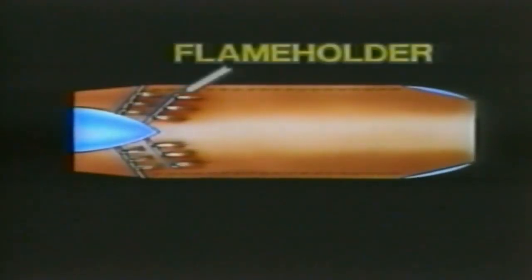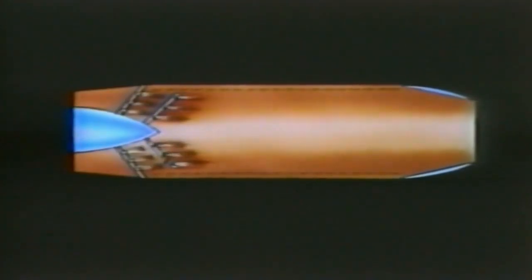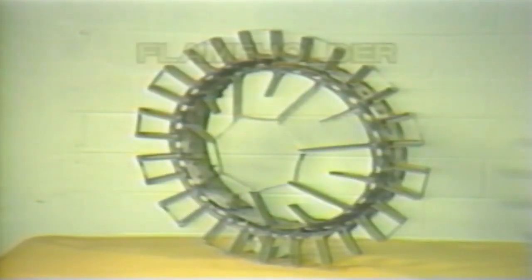The flame holder. It sits right in the path of the gases as they enter the combustion area. Its purpose? To create turbulent gas flow. Maybe that's why it's the ugliest part of the entire engine. After looking at so many smoothly contoured and airfoil-shaped parts, this is truly a strange-looking sight. It's a network of annular and radial gutter-shaped pieces that slow the gases down even more and provide thorough mixing of the fuel and air so the flame will be held within the afterburner and not be blowing out the exhaust nozzle.